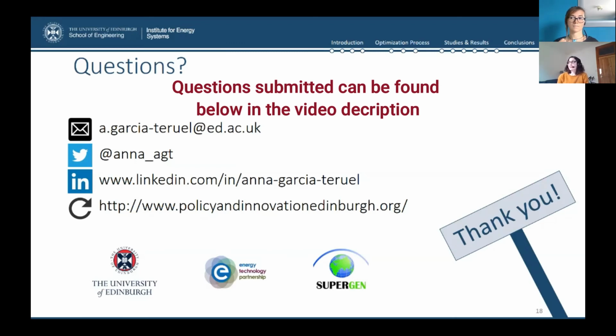situation. And secondly, defining this characteristic length, you're introducing additional uncertainty, because the characteristic length or width of a device will depend on the type of the device, on the shape that you're using for that device. And so it makes the results for different types of devices less comparable, in my opinion. So I would not recommend using that measure for wave energy converter geometry optimization.